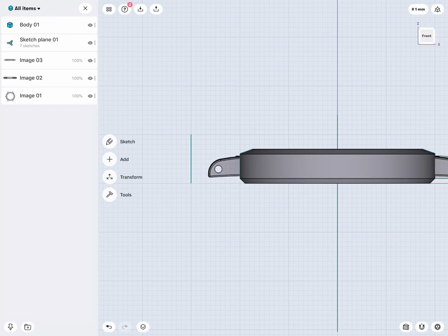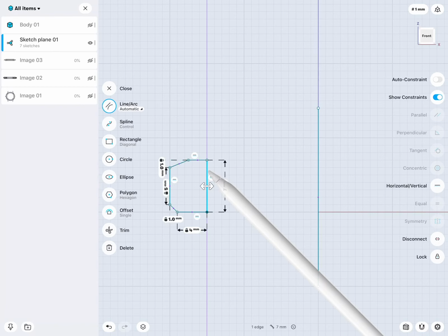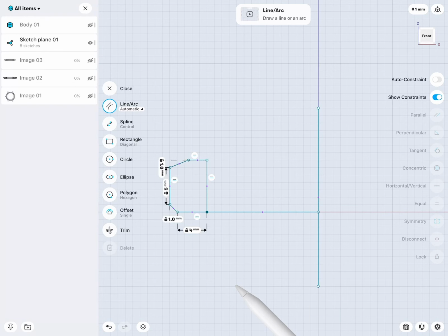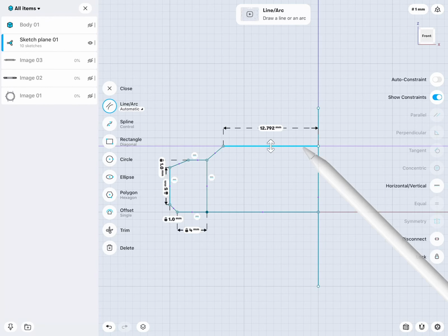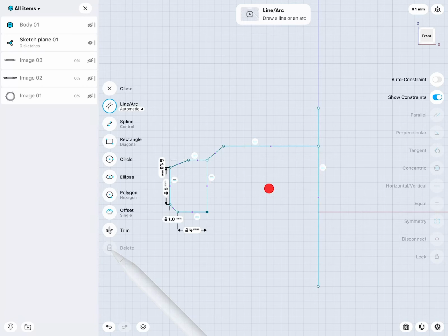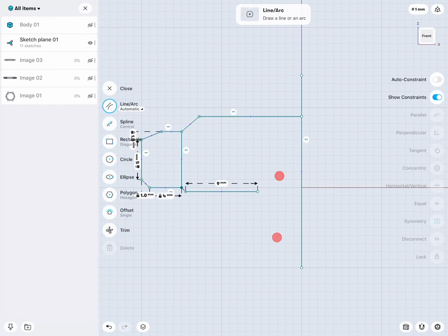Let's say we would like to build the glass part. So I can continue with the sketch. Simply draw a horizontal line till it meets the line on the right. Draw a line up, draw a line horizontally over, horizontal, vertical, horizontal. Actually here, this one we delete. We just do this. It's kind of like for the battery. Insert, go over, horizontal. Here, this line I lock. I don't want this to move anymore.